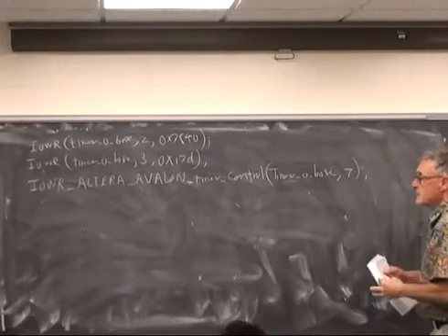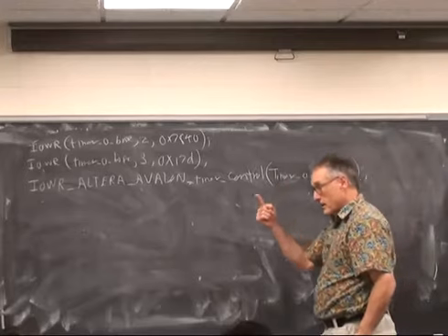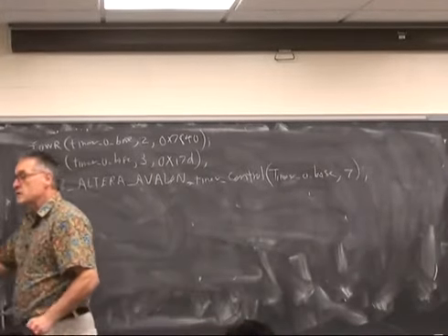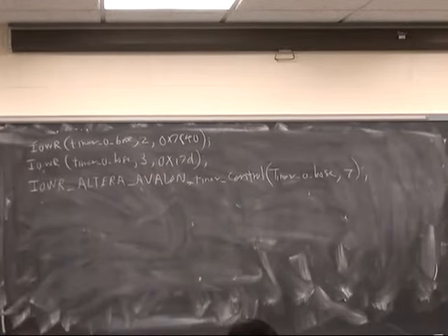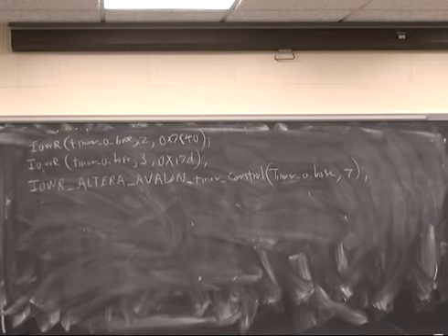7 here means set the low 3 bits, which correspond to start the timer, make it continuous so that as soon as it hits 0, it reloads the starting value and starts over. So we get a continuous half-second time base, and bit 0 turns on the interrupt. So it allows the system to interrupt on timer equals 0.